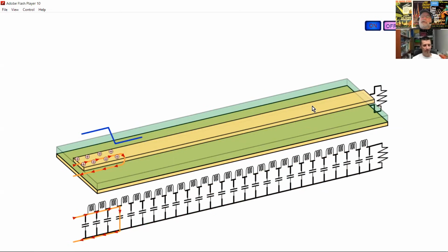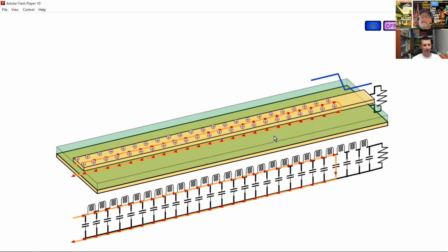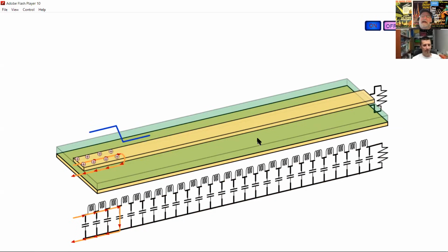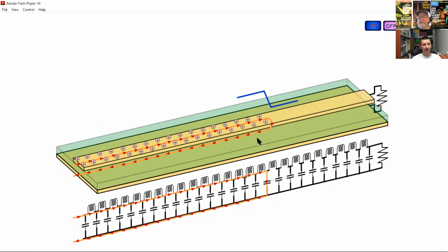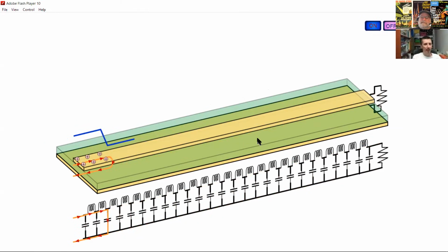That means this side of the board will be a different voltage than this side. And when you have that transient current, it's going to excite that gap and that higher inductance, and we're going to see a voltage noise peak. So, but the return current will go around the gap, or it will cross the gap?